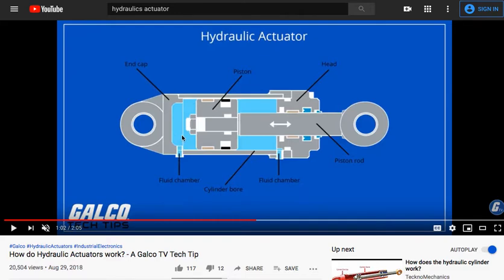So what happens is the hydraulic pressure will be pushed in under pressure. Let's say you want to move this outward, so you want to move it going out this way. You would force the pressure into this side, which would push this piston and push the surface that's connected to this piston outward that way.